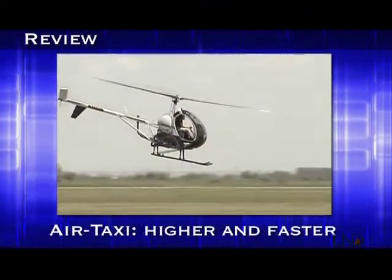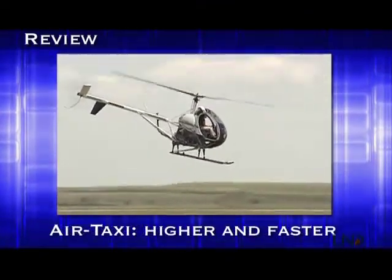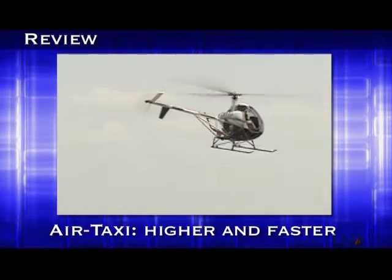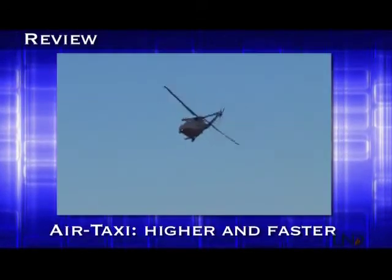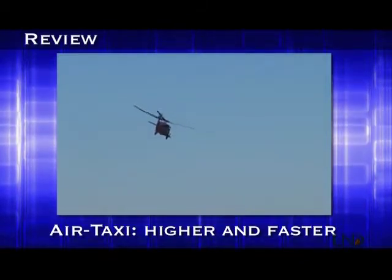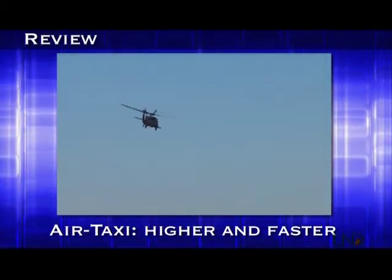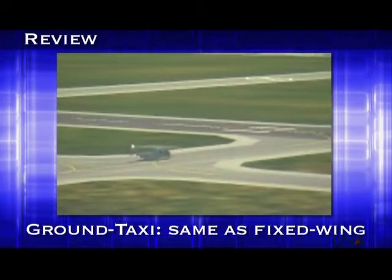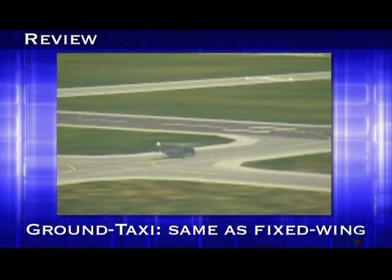When air taxiing, the helicopter will move above the surface up to an altitude of 100 feet AGL and speeds greater than 20 knots. This is often the preferred method of movement because it's faster than ground or hover taxiing and is used when helicopters have a long way to go, such as across an airport or to a distant helipad. Ground taxiing is basically the same as what fixed-wing aircraft do.